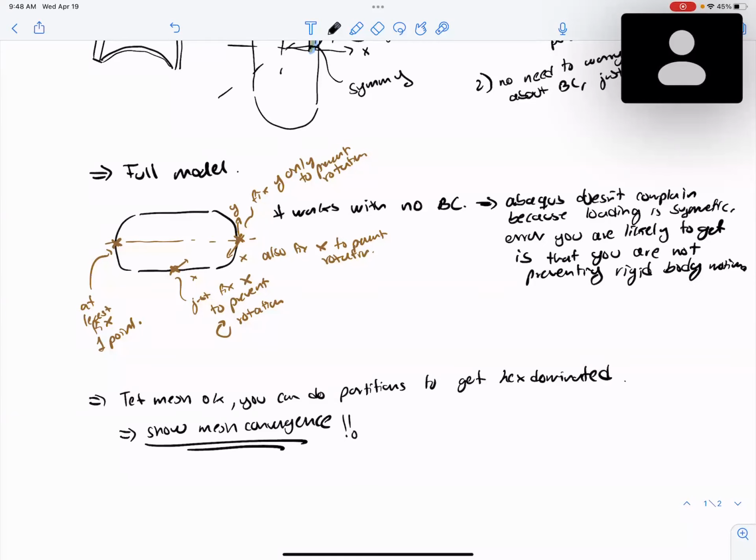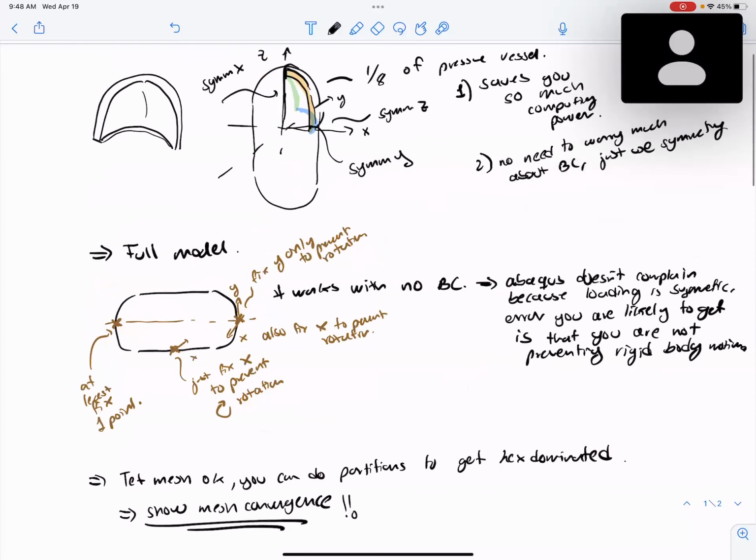What else? There's an analytical solution. That's another thing, kind of contrasting with the project, for example. For this case, really a finite element is not needed for the ideal pressure vessel. For that one, you can just compare to analytical solutions. When do you actually need the FE?